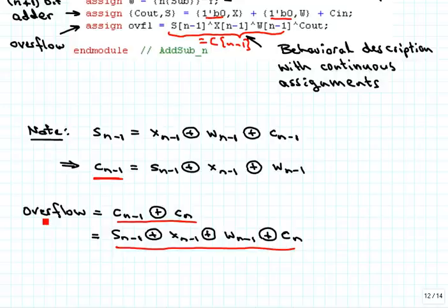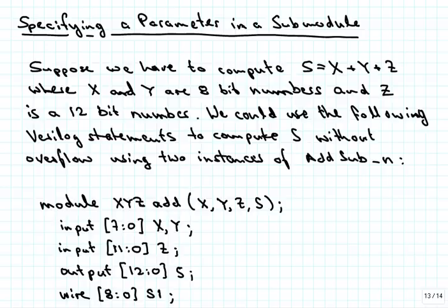Now we were trying as much as we could to actually parametrize those implementations of those adders to make them n-bit adders with just a parameter statement. And we have been generally setting this to n equal to 32. But if you would like to instantiate one of those adders with 16 bits or with 8 bits, then we would like to have a mechanism by which we can change that parameter n easily.